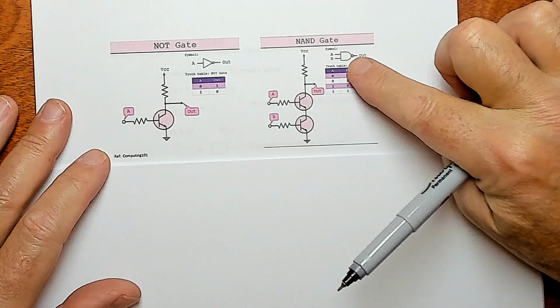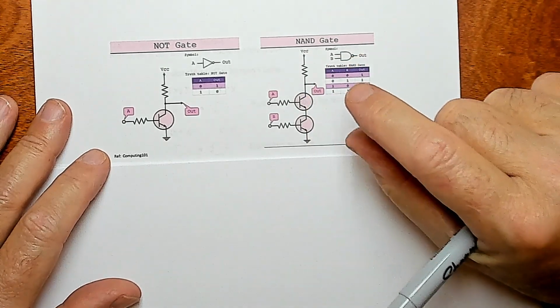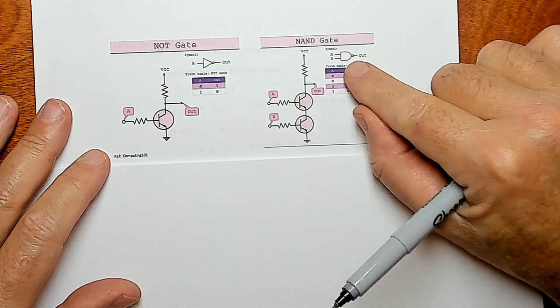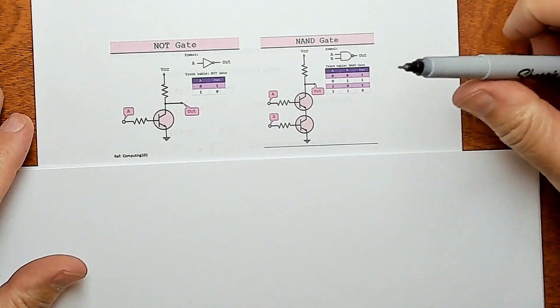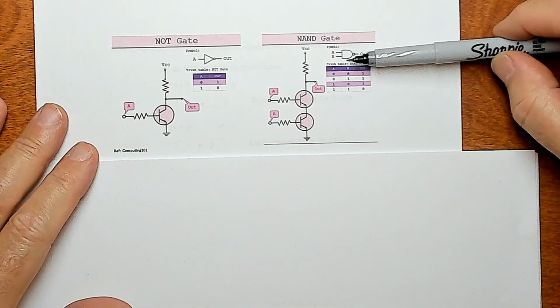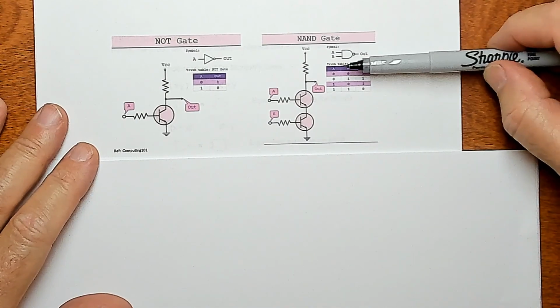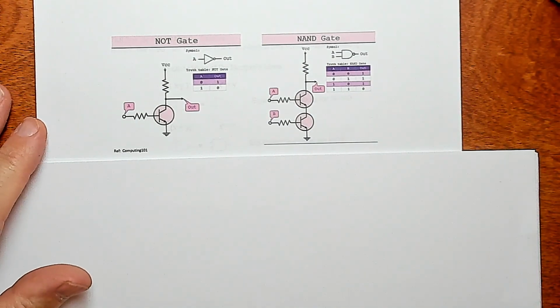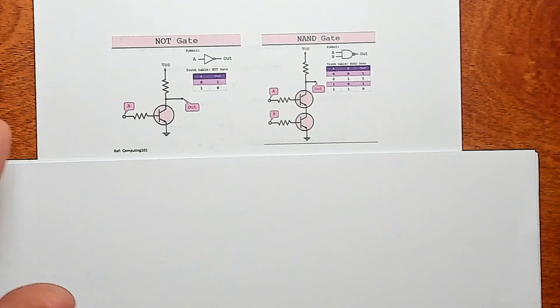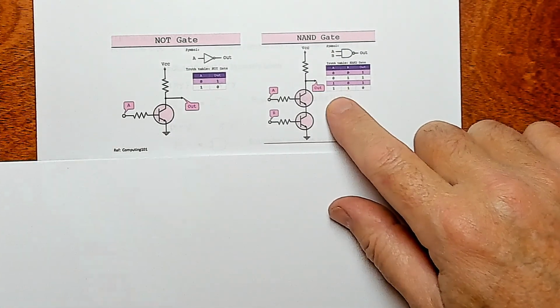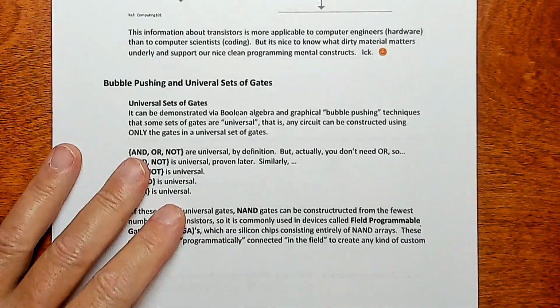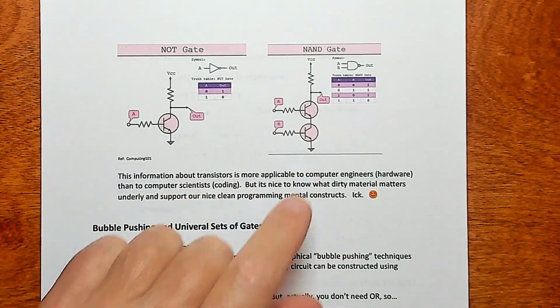So this is a great little gate. It takes up very little space. It takes up less space than AND and OR would take up. Unfortunately, the situation is we started with AND, OR, and NOT. That's just how we humans think. That's sort of our starting axioms, so to speak. But it turns out that this is easier. So what can we do about that? How can we leverage the fact that NAND gates are so small?